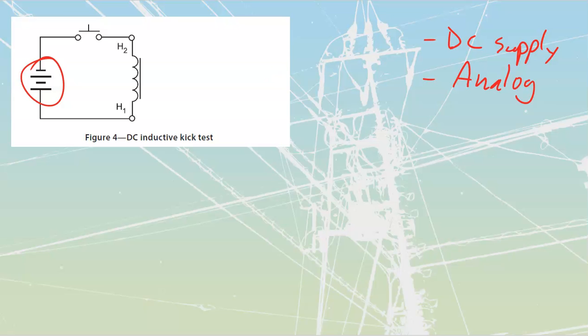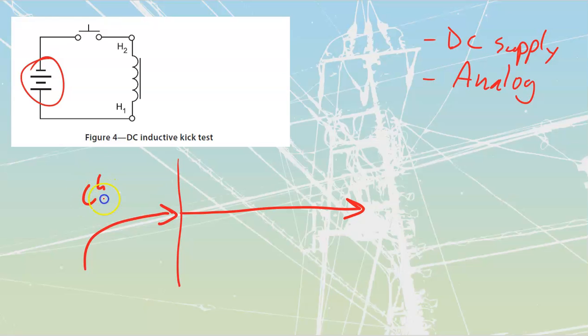Absolutely, we've done stuff like that before, where we said that inductor is going to oppose a change in current. What's the current right now? It's 0 amps. When I apply this, we're going to see my current rise to a steady state. And once it's at a steady state, it's no longer changing. So from here on out, it's going to be steady. Right now, for a brief instant, we're going to have change, and then steadiness. This is going to be critical to understanding what's going on here.